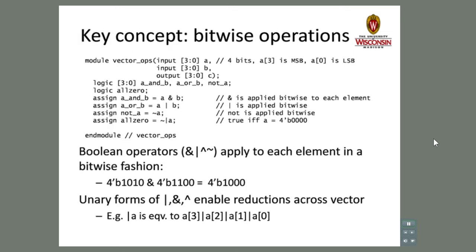In assign statements, vector arguments to operators like AND, OR, and NOT will be processed 1 bit at a time, so that the most significant bit of the left-hand side is set to the most significant bit of each argument applied to the Boolean operator.